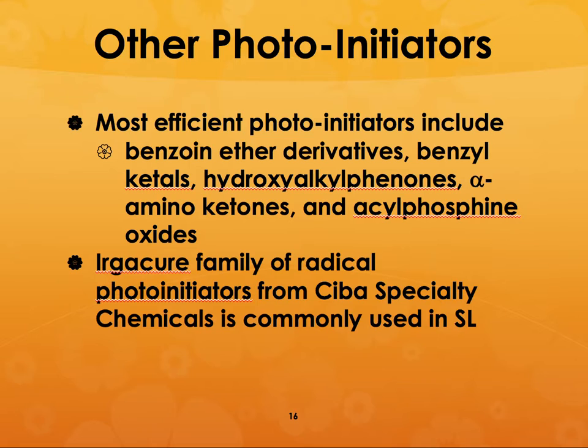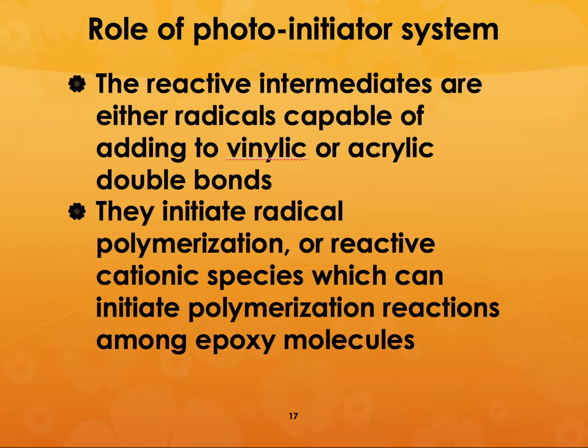In the case of some of the earlier resin systems, they were made by Ciba. It used to be called Ciba Geigy, but it became only Ciba, and they were some of the earliest producers of the stereolithography resin systems. And I believe that it might have been taken over by 3D Systems. Now, the takeaway is that these photoinitiators should be able to initiate the radical polymerization, and it can initiate the polymerization reactions among the epoxy molecules so that all the epoxy molecules are linked together to form a very strong chain.